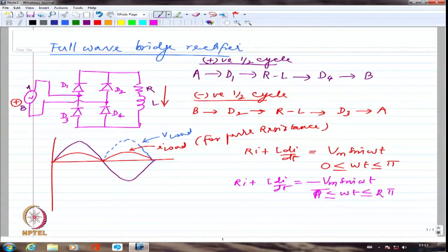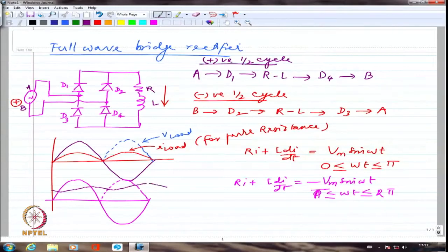If higher and higher inductance values are seen, you would see that if this is the voltage, that is the supply voltage, the rectified voltage is somewhat like this. I am going to have actually the oscillation in the current really minimized. So I may have something like this, then it may increase, again decrease, again increase, decrease, and so on.